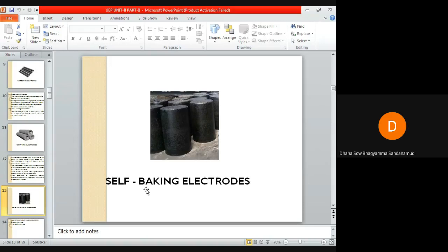They consist of an outer casing made up of electrical conducting material, and they have inner radial and vertical ribs. Carbonaceous unbaked paste is supplied to the casing, in which the paste is baked to a solid electrode by means of electric current supplied to the electrodes.